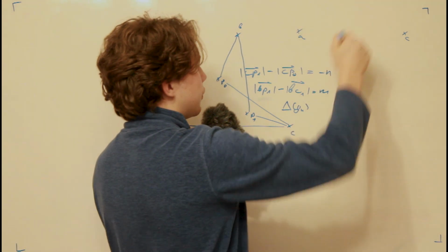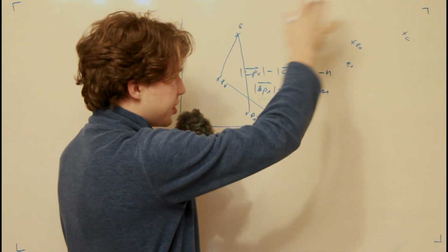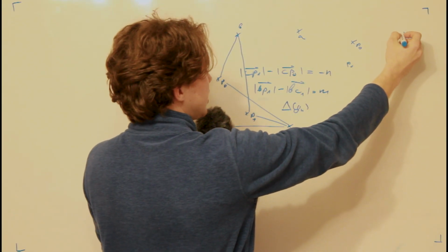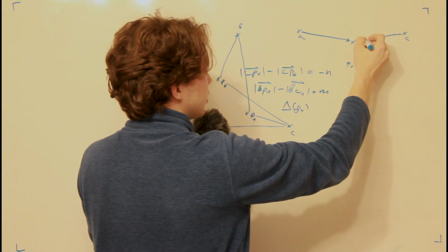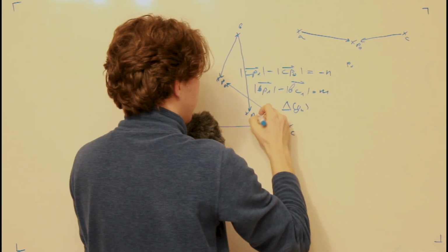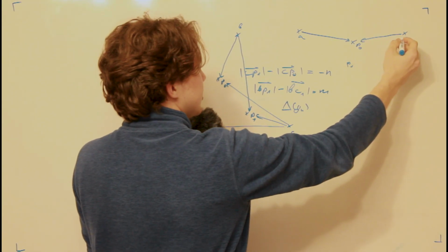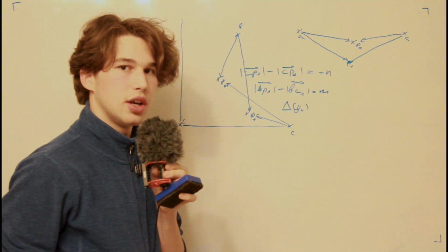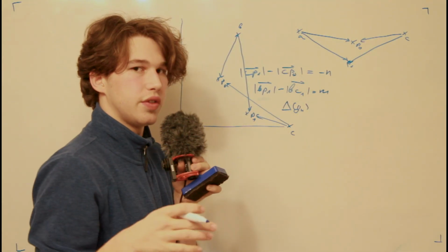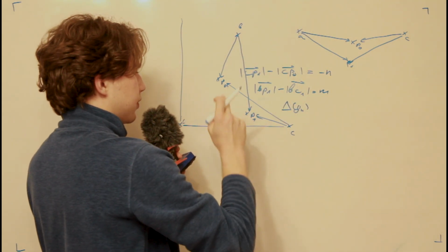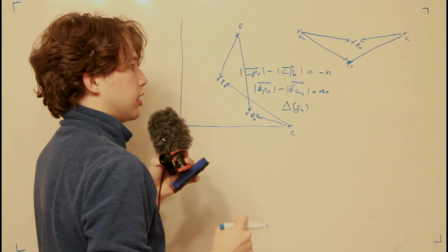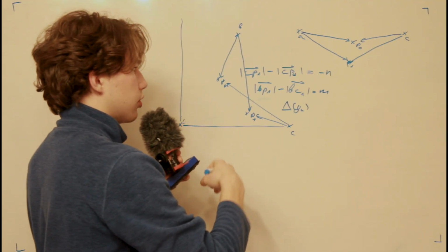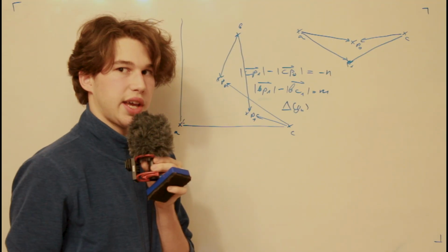But anyway, let's move on to the vertical simple feature here, to this vertical operation of Floaty. It's the same thing here. You just take these two vectors. By the way, we need arrows here, because these are vectors. And do the same calculation, and you will notice that it's just the same. You calculate just the difference between the vectors, between our anchor points and the motors of Floaty, and you just need the difference to say to the motor, run back or run forward, just like give or take a certain amount of rope.